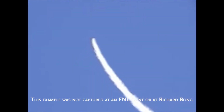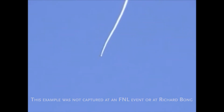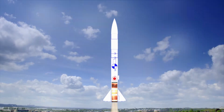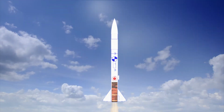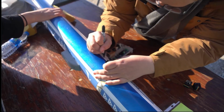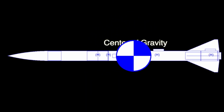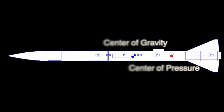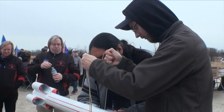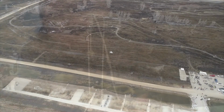Also, both center of gravity and center of pressure will change as the motor fuel is burned in flight. Luckily, the center of gravity generally moves forward as the solid rocket motor burns, causing the rocket to become more stable. For the competition, you will need to mark your airframe with the center of gravity using a crosshair and the center of pressure using a bullseye as shown in RockSim. Make sure to mark the actual center of gravity found by testing, not the simulation center of gravity.